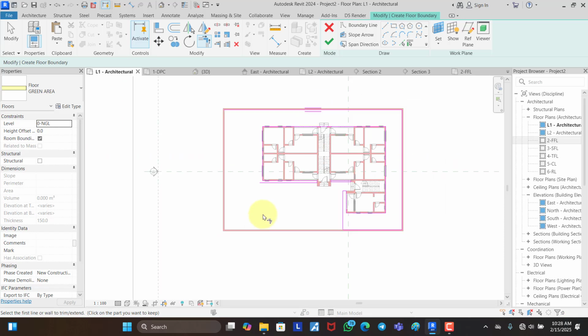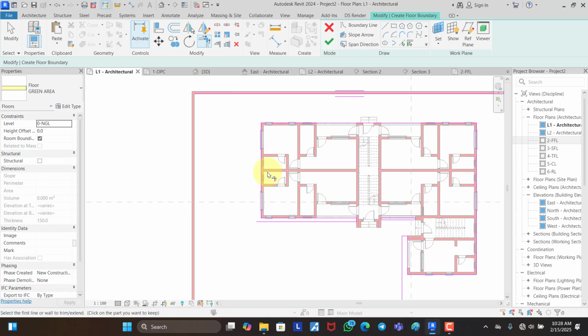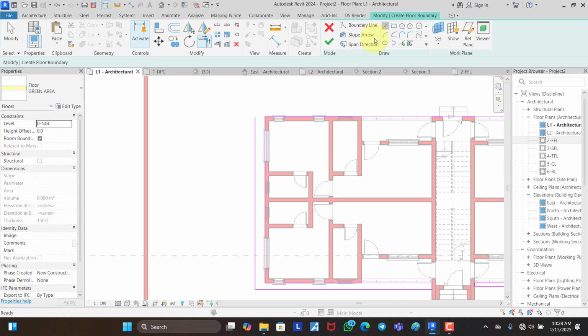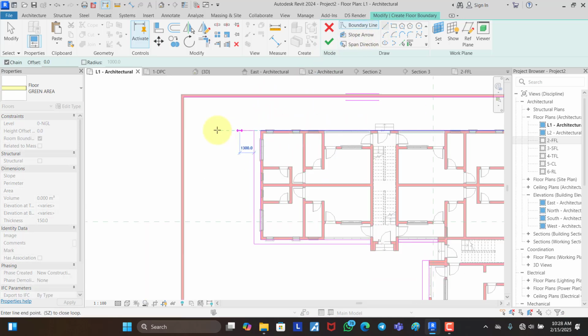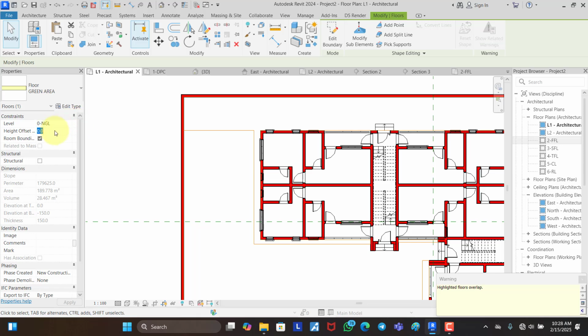All right. So we have this. So let's say we take offset of 600 here. Sorry, offset with copy. Important. Very, very necessary. So we have this and this. Click on good, then take offset 150 above the natural ground level.